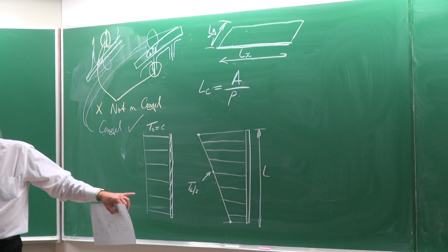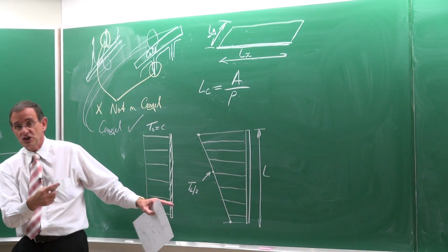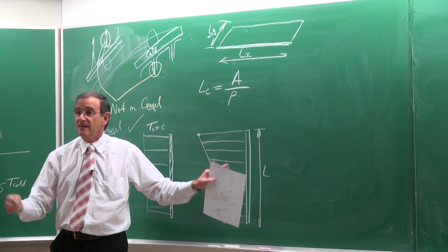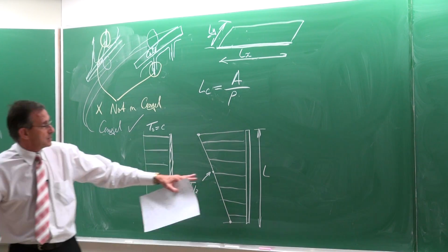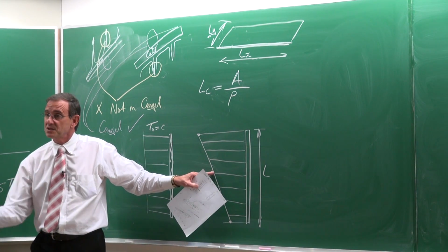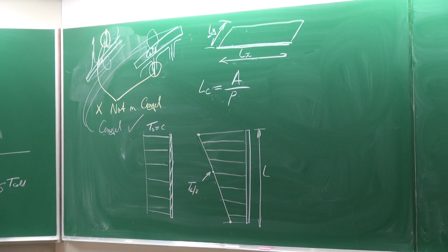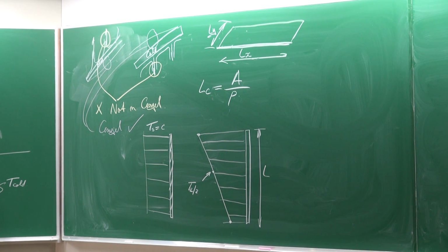Now normally when you start a problem like this, you wouldn't have this temperature, which means that you will have to guess a temperature, work the problem through, get the temperatures, and then iterate. So this problem is specifically much more sensitive to your starting condition and this specific temperature here. So please take note. This is one where I can catch you out in the exam. For the constant heat flux case, you have to be very careful. Right, that is sort of the use of table 9.1. Let's do examples.